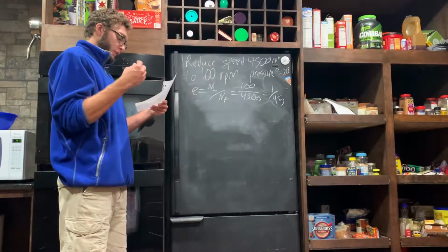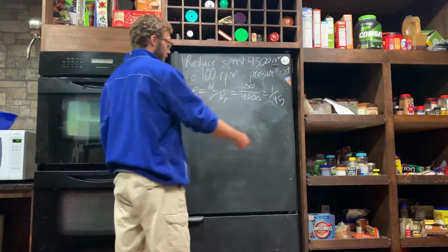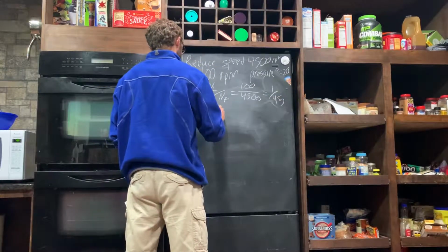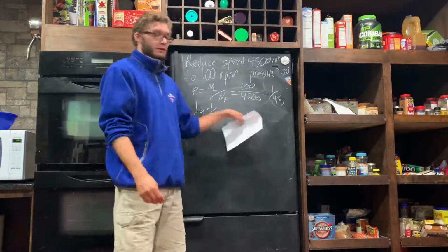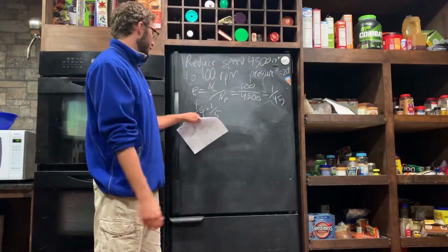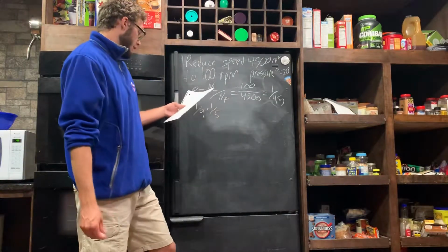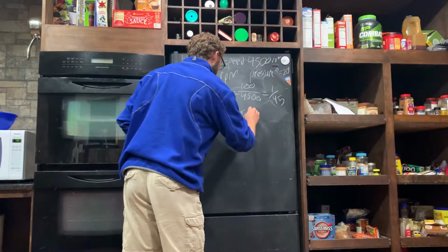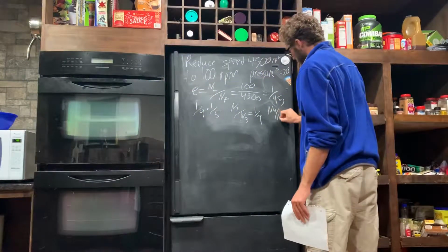We're going to break this number down into 1/9 and 1/5, because we have two different sets of gears, as I showed earlier in the drawing. One is going to have a 1/9 ratio, the other a 1/5 ratio. So the input will be 1/9, and the right side of the shaft will be 1/5.